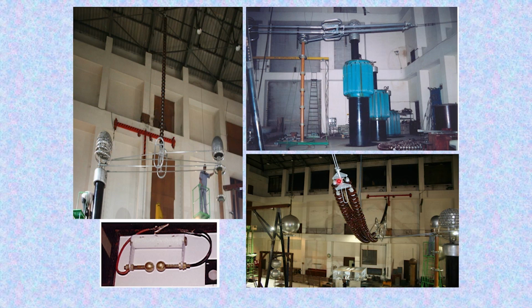Quadruple is 4 insulator strings connected together, particularly used for very high and ultra high voltages, 765 kV and above. This string has to be simulated as per the field arrangements. You have all the necessary hardware like the yoke plate, the arcing horns and the corona control arrangements. You can see here the corona control rings, the end fittings, the metallic yoke plate and other things, all the accessories similar to the tower configuration where the insulators are strung. This is done in the laboratory: using the sphere gap arrangement, we connect across each insulator disc and the voltage is applied. The 5 breakdown readings across the sphere gap are taken.